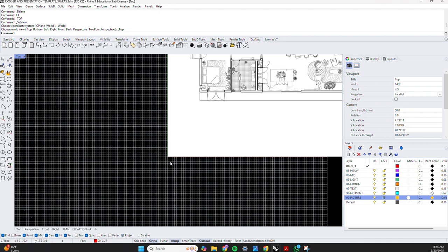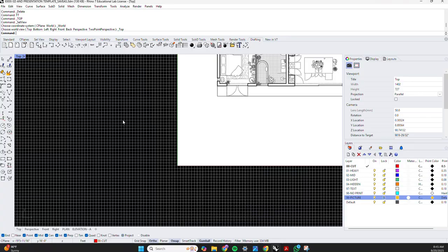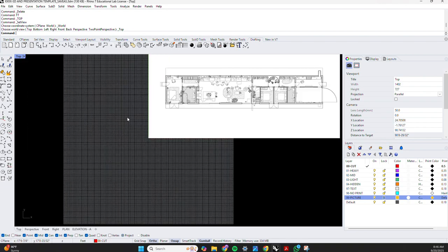we can see that in this grid, that is one of the base settings that you can either toggle on or toggle off in Rhino. The center of this grid, as it always appears in Rhino, is what is called the origin point. So it is the coordinate point of 0, 0, 0 on this axis.